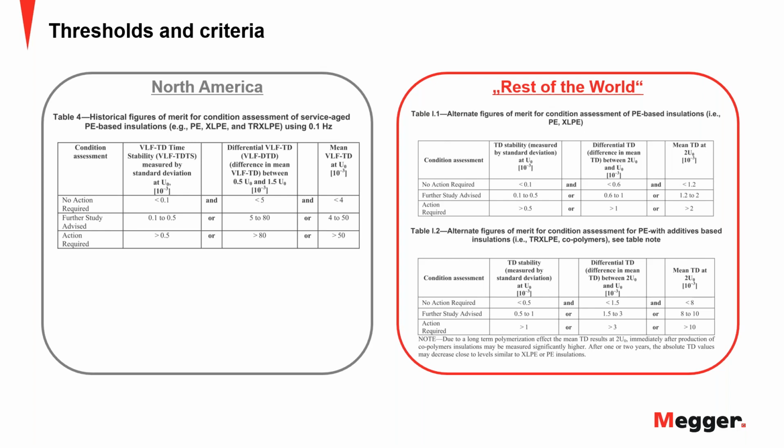Well, as I tried to explain, I could give you a very short answer: not much, or nothing. The tan delta is really not an effective, useful test on newly installed cables, to put it plain and simple.